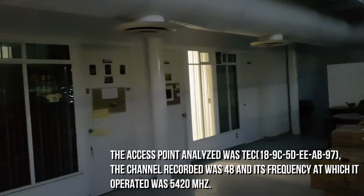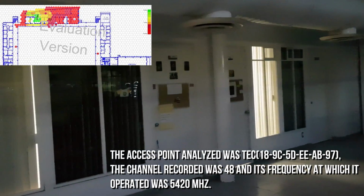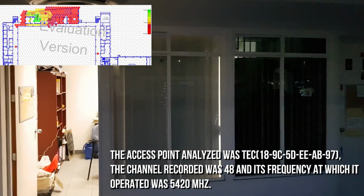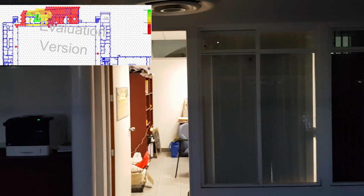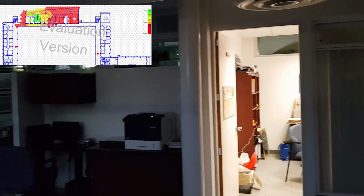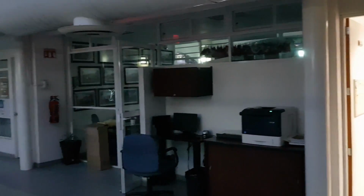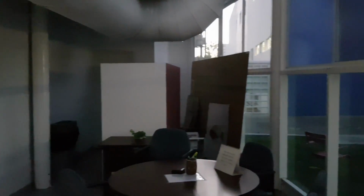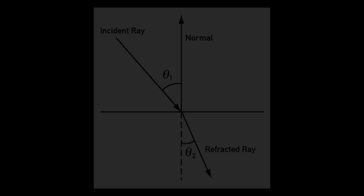The main propagation phenomenon observed in the whole building was diffraction, because most of the building consisted of walls and glass windows. Furthermore, the furniture inside the classrooms and offices, as well as the design of the building, had sharp edges. This means there was a lot of diffraction in the wave propagation. As a result of the latter, the signal from the access point was stronger near windows and open doors.